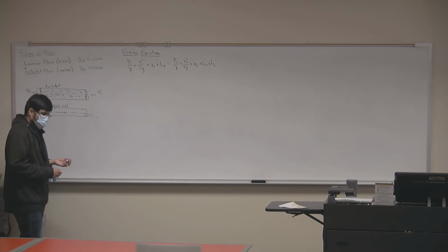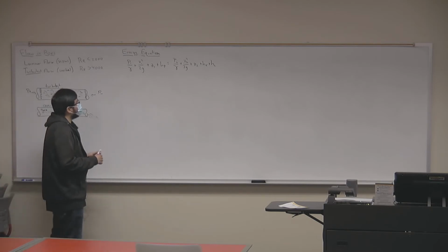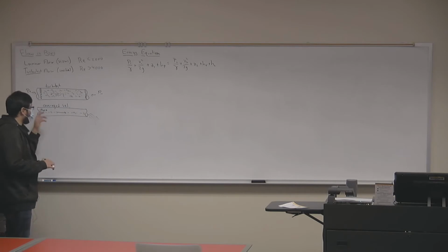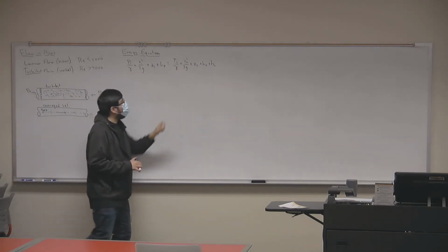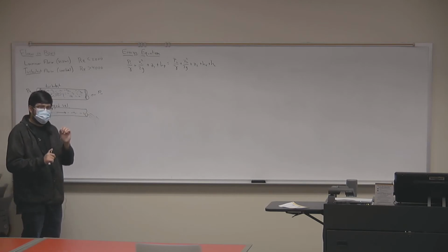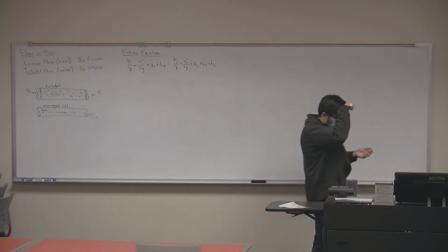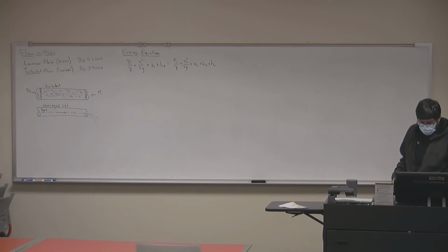Now the energy equation expresses the law of conservation of energy, so it is a law, right? It should apply to any system. In this case, this is a case of steady uniform flow. And what we can say is, if my average velocity in the pipe is steady, then I can treat it as steady and uniform. Because in this energy equation, this velocity term will actually be an average velocity term, and we should still get correct results. They're not going to be exact and precise to the dot, but they'll still be applicable for our work. And that's really what we want to lead you to study, right? Our work.